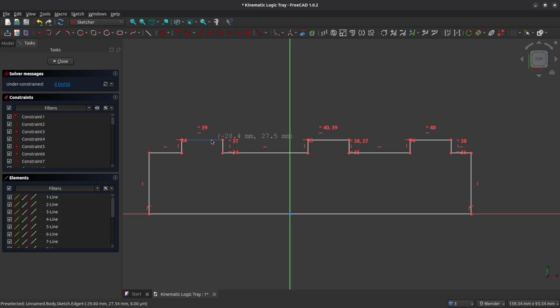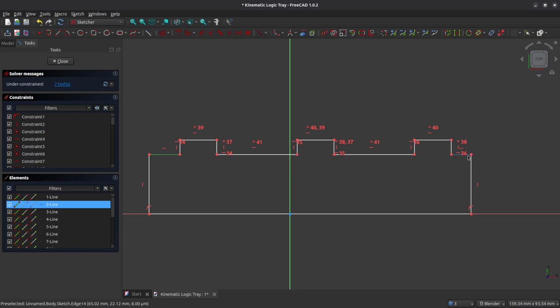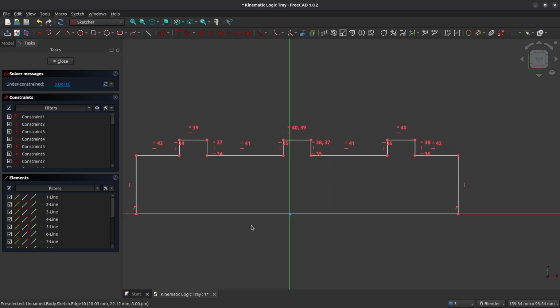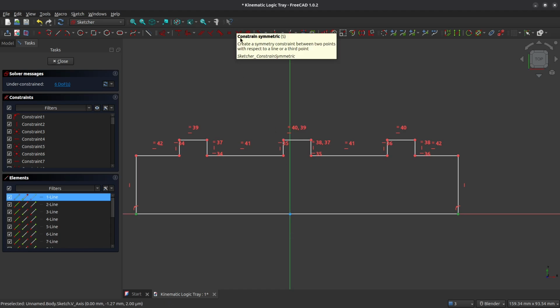And now we're going to set these 2 middle gaps here between the first and third tabs. We're going to set them so that they have an equal width. So we've now mostly constrained our shape here. Oh, and we're going to set these 2 outside spaces. We're going to set them so that they're equal. All right, so now we have a symmetrical design, and the tabs will sit symmetrically. So let's make the entire design so that it is symmetrical with respect to the y-axis.